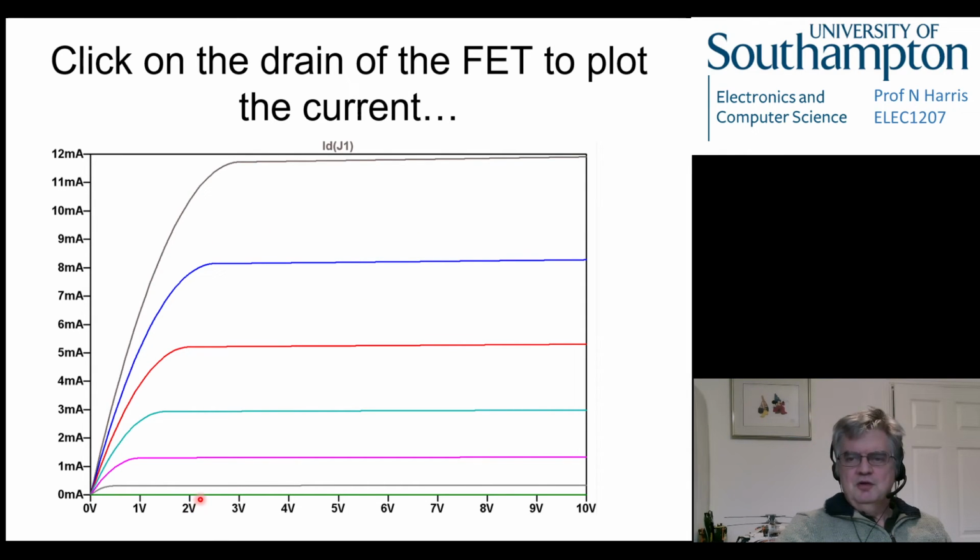And so every time it's run, at VGS equals 0, we get this green line at the bottom, which you might not be able to see, telling that no current comes out, and then we increase to 0.5, 1, 1.5, 2, 2.5 and 3. Oh, sorry, it's the other way around, isn't it? With 0 volts here, we get this current out, and then as we decrease it down, head towards the cutoff voltage, we'll get no current through.